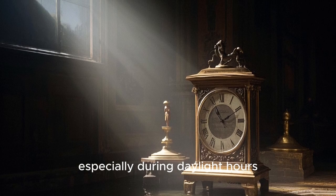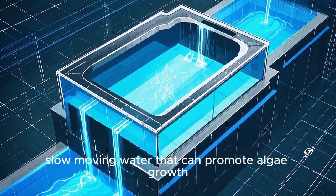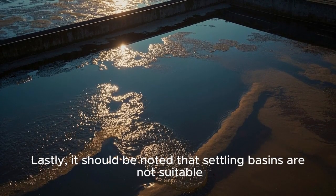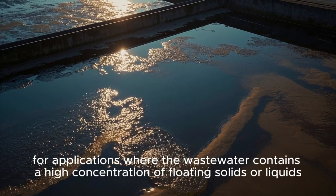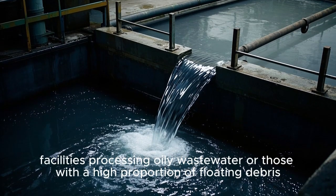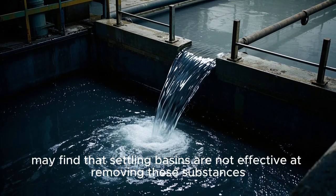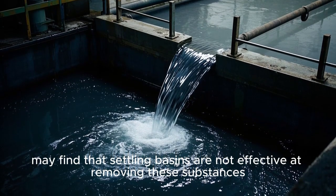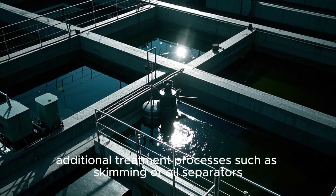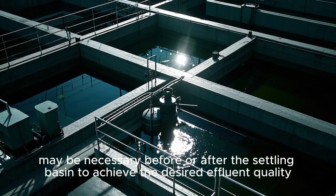To mitigate this issue, it's crucial to minimize the time that water spends in the settling basin, especially during daylight hours, and to ensure that the basin is designed to prevent stagnant or overly slow-moving water that can promote algae growth. Lastly, it should be noted that settling basins are not suitable for applications where the wastewater contains a high concentration of floating solids or liquids. For instance, facilities processing oily wastewater or those with a high proportion of floating debris may find that settling basins are not effective at removing these substances. In such cases, additional treatment processes such as skimming or oil separators may be necessary before or after the settling basin to achieve the desired effluent quality.